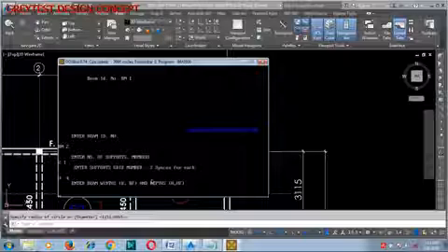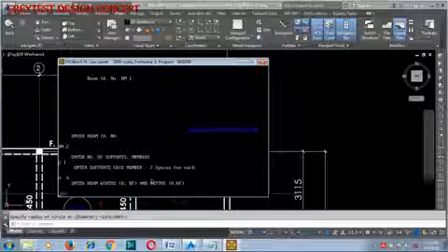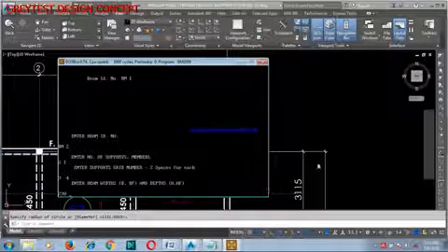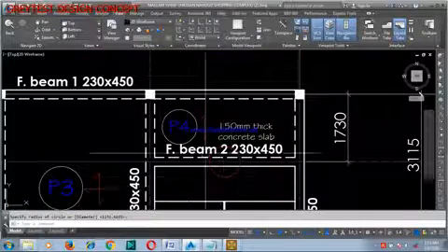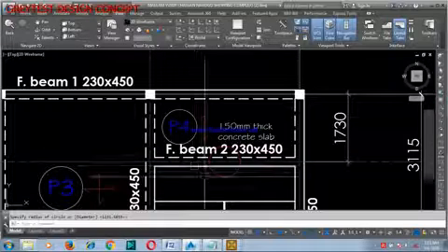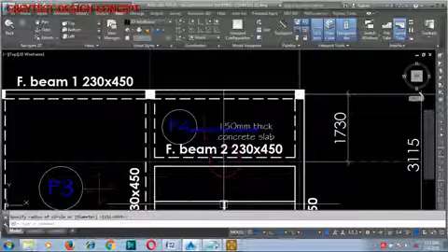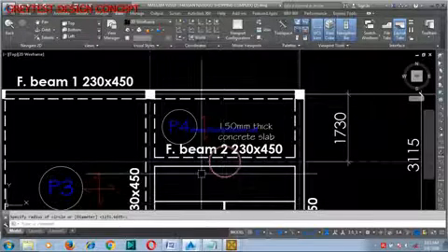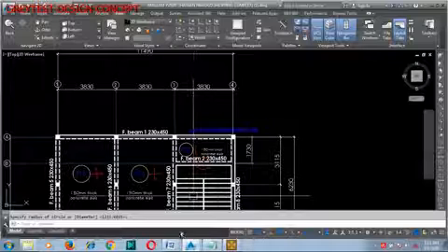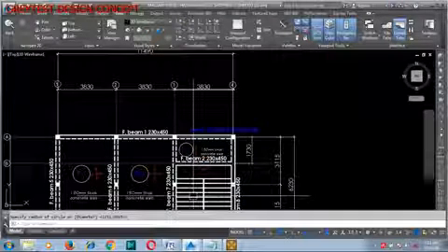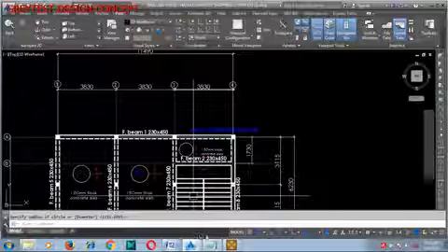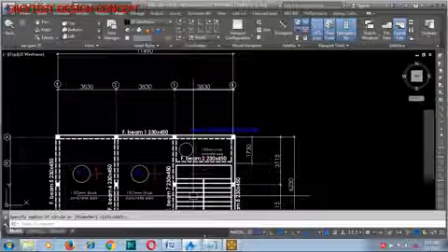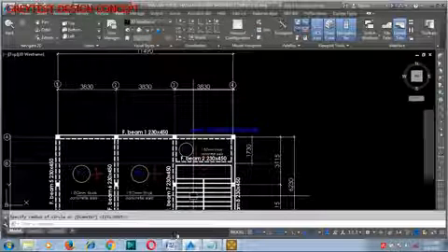Okay, what is the width, which is 230? What is the BF? That's breadth of flange. You know, here this beam is actually a T-beam. Okay, and the span is 3830, so it's definitely what we are going to use. We don't have a different span, so that is definitely going to be our maximum span.